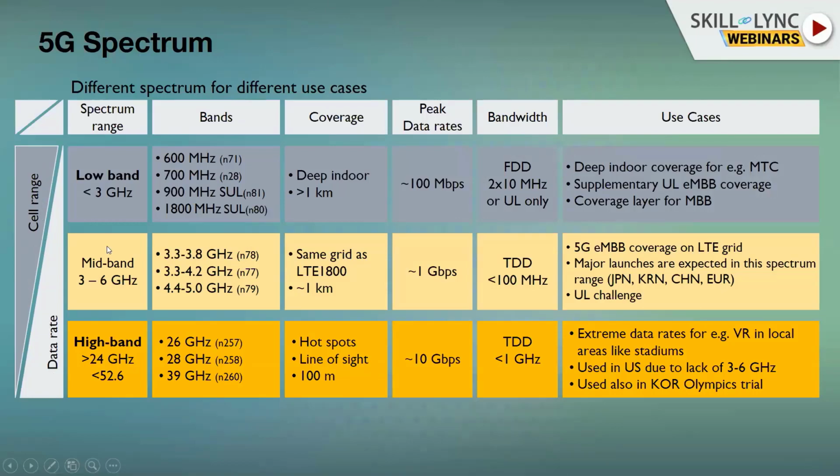I will explain. 5G is the first ever radio system that is designed to support any spectrum between 400 megahertz and 90 gigahertz. So 3GPP has decided that NR, or New Radio, which is 5G, will from Release 15, as explained before, support operation from below 1 gigahertz up to 52.6 gigahertz, as well as operation in both licensed and unlicensed spectrum.